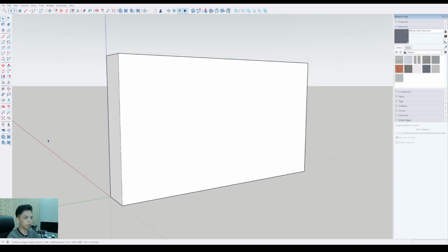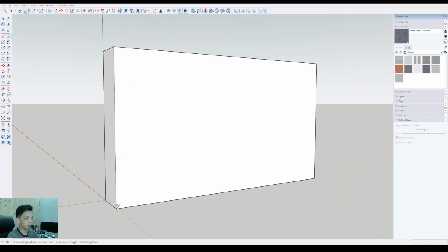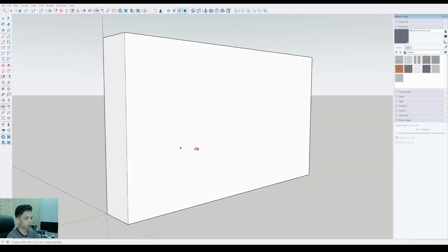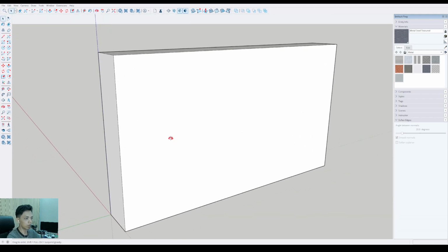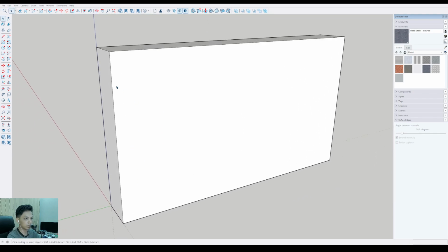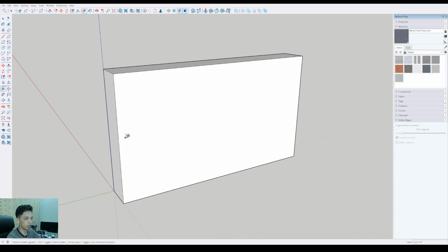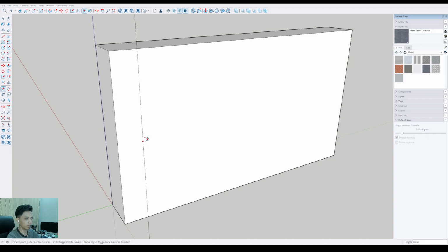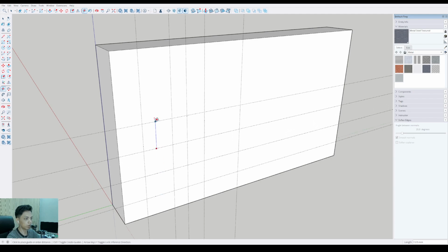Okay, then we have to make the contour with the freehand tool. We can start from the corner at the bottom, and then we can draw another. We can draw it by our design of the contour, but I suggest you use the tape measure tool. Start from here, and then you can track the measurement of the contour of this hillside. You can draw it manually with the tape measure tool, so you can get the perfect contour.